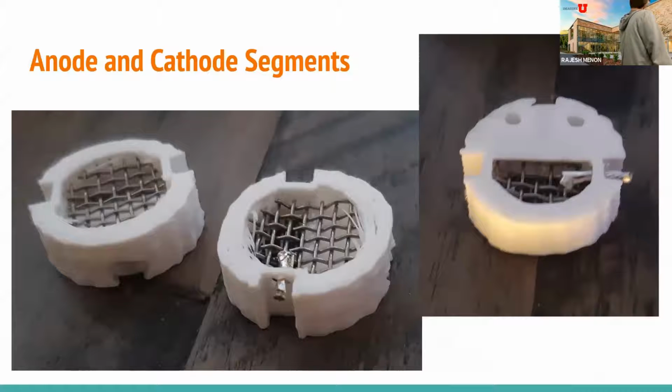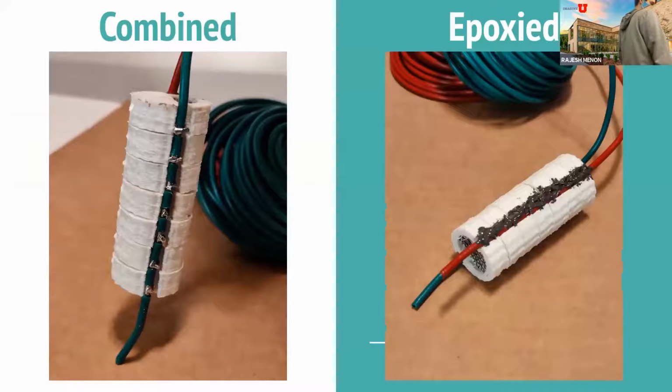Here are some photos of the anodes and cathodes that are in there. Like he was describing in the mock-up, you can see there's a membrane in the middle, and that separates the oxygen and hydrogen so they can't immediately recombine. And then the oxygen comes out one end, the hydrogen is allowed to flow from cell to cell. And then there are attachment points for the two nickel grids. Here's everything soldered together before we slid it into the tube. We ground it to really shut the solder down. So we put all the cells together and then epoxied them and then slid them into this tube and then drilled some vent holes for the oxygen to come out.